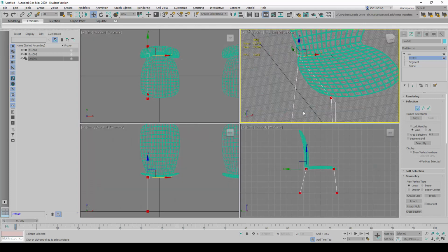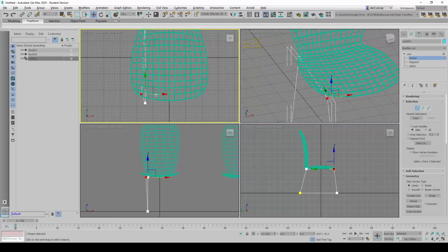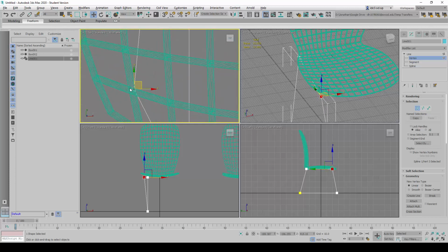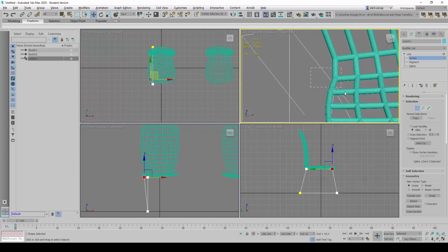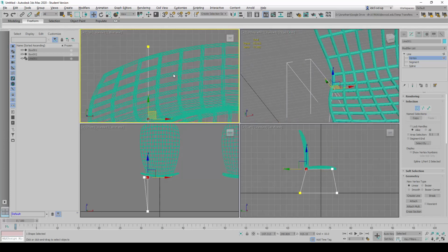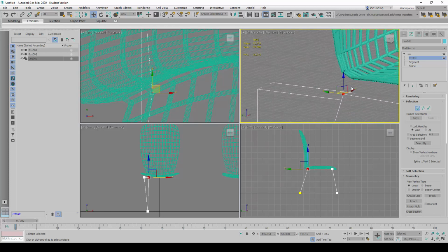Then I will select this point so that I can adjust it closer to one side and inwards, to let it reach or touch the corner points here. I will use this intersection edge as the location point, and I'm going to go back to this one now and look for a good location so that, in real world construction terms, it can be anchored or welded nicely here. Okay, somewhere down at this point here.